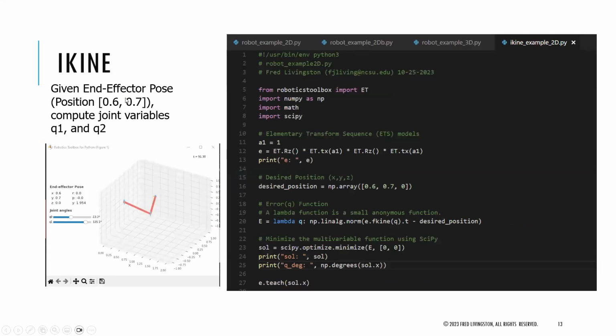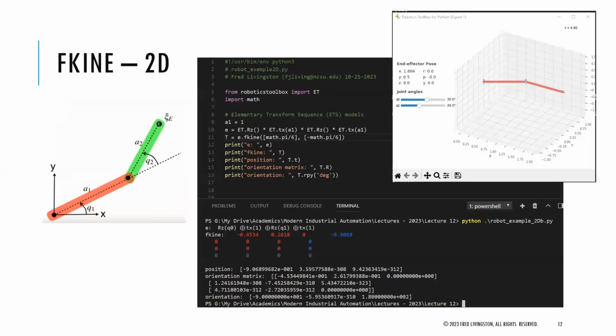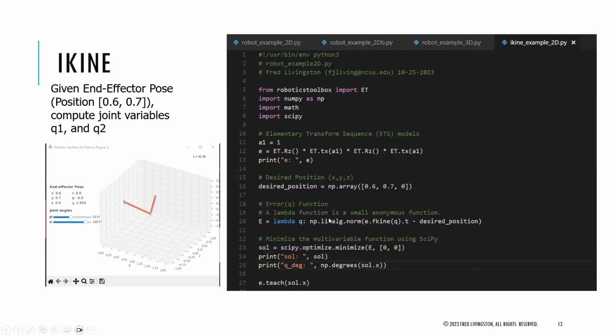And this is the inverse. This is one method to do the inverse. Again, there are multiple ways to do the inverse. I have this T matrix here, and so I can just invert this T matrix, and I can also do the inverse kinematics, and then back compute your orientation and PX, PY, PZ. That doesn't always work. And so this method here is doing an optimization, and this may not always work either, but it may give you a solution that gets you close to there. You may not converge exactly, with the error going down to 0.